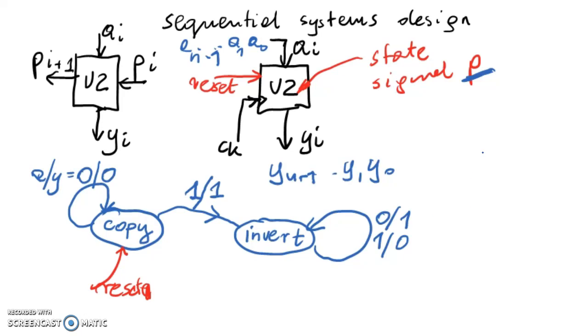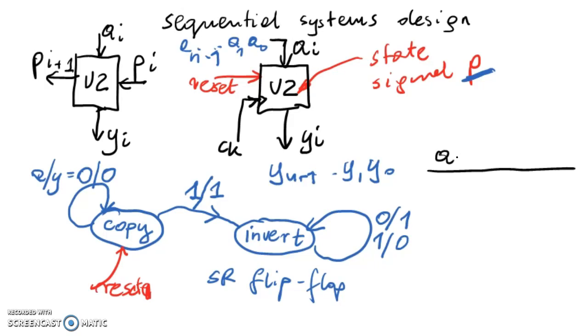Let's suppose you've got the SR flip-flop. It is enough to have a single one because you've got only 2 states. And the state transition design table is the following. You've got A_i here, let's call it A, and then the state, which you must associate with the SR flip-flop, which has Q of t as a state.